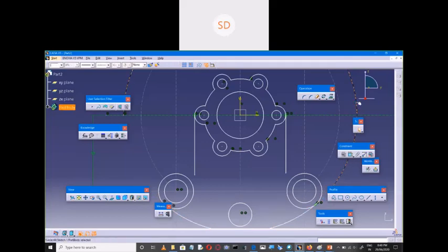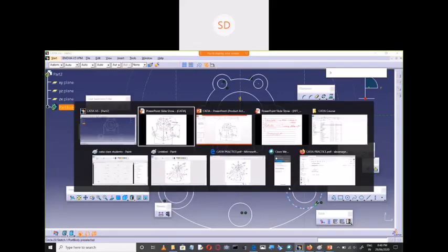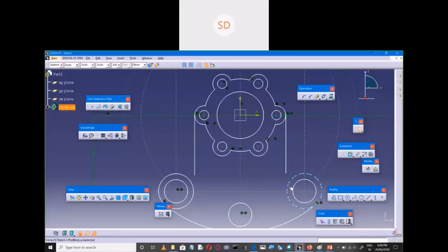Now once the required portion is done, you can directly delete the other portion. So you don't worry. Now you need to create a fillet here. That is the corner. So what is the corner radius? The corner radius is 18. Okay. Now let us go for corner. We have some options here: trim all elements, trim first element, no trim. Let us go for the no trim option here. We'll discuss what no trim is and all those things. Select first object, second object. Now you need to provide the radius here. The radius is 18 mm. Okay.